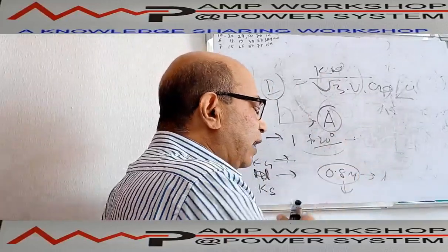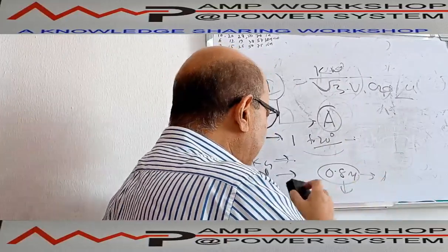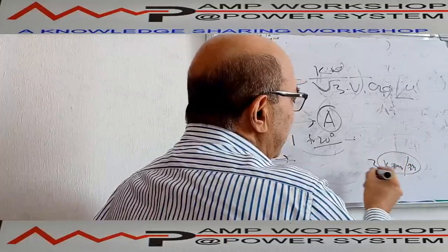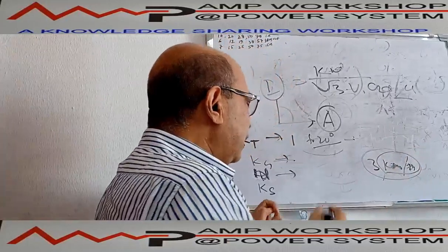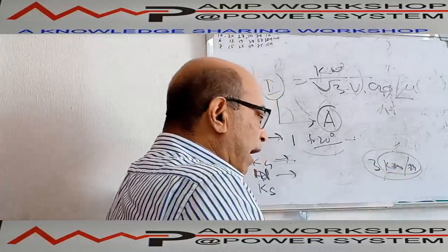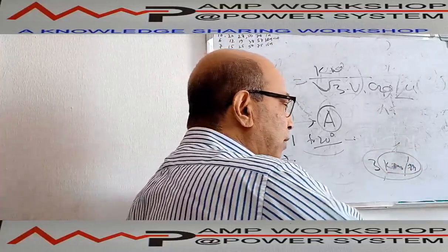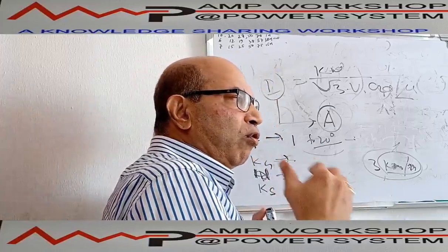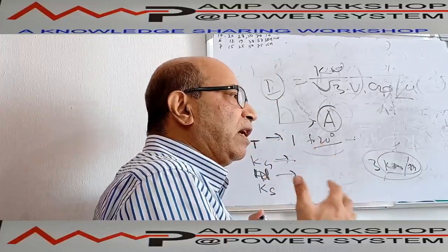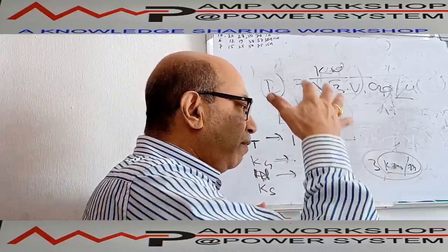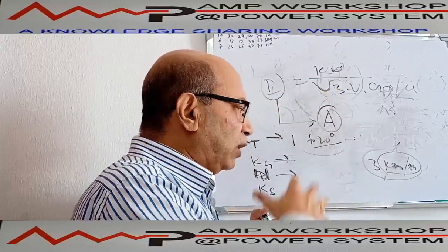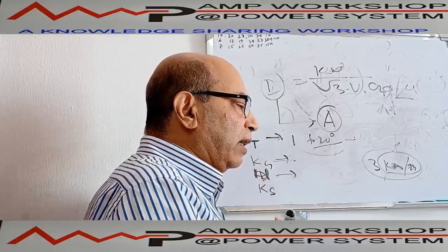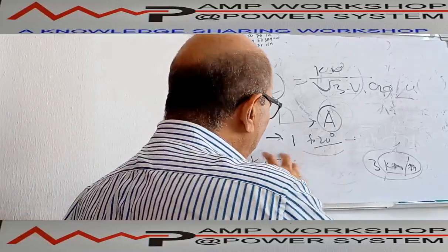So that way the derating factor is decided for the depth. For the resistivity derating factor, generally if the value is 3, then the factor is 1. But if the value is less than 3, as the resistivity gets lower and lower, the soil is more conductive, so the factor will increase. If the K value is more than 3, it will be derated. This factor we can also get from the table. So these are the 4 derating factors.